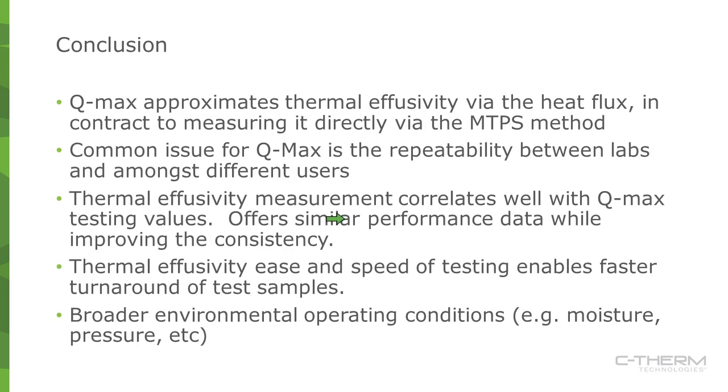Qmax, again, is approximating that thermal effusivity via the heat flux, in contrast to measuring it directly with the MTPS method. The biggest point of difference is the repeatability between labs and amongst different users. Thermal effusivity measurements correlate well generally with Qmax testing values, but offer a substantially simpler method to running it with greater ease of use and speed of testing, as well as generally being more adaptable to a broadening operating conditions.